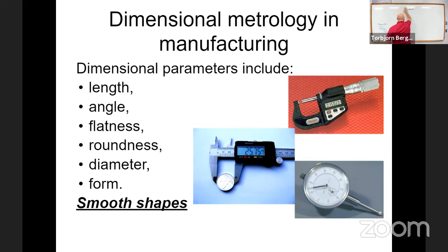We measure to control our processes as manufacturing engineers, or if we're at the early design phase, we measure to design our parts. So we may do an experiment to see, does the part of this size actually function? But once we're in the manufacturing state, once we're making product that we're intending to ship to customers, we're almost only measuring to control our manufacturing process or to ensure that we don't ship crap to the customer. Measurement uncertainty is going to make it so we don't know if we're shipping crap to the customer all the time.